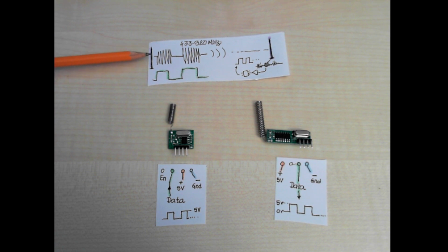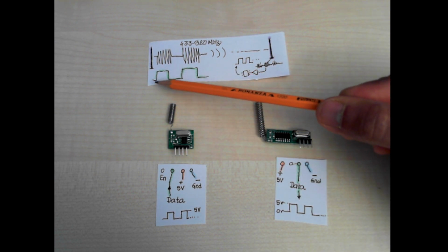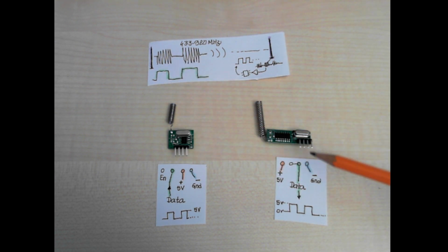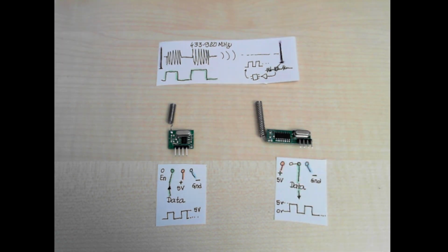In fact, even more specifically, this form of keying is called on-off keying, because you either send the carrier wave or you send nothing. And the waves reach the receive antenna on this side, and there is electronics here which amplifies the signal, filters it out, and then on the data pin here provides a corresponding signal out. So if everything works fine, what you pulse out here on this data pin should appear transparently on the data pin here. So this is the idea of these two modules here.